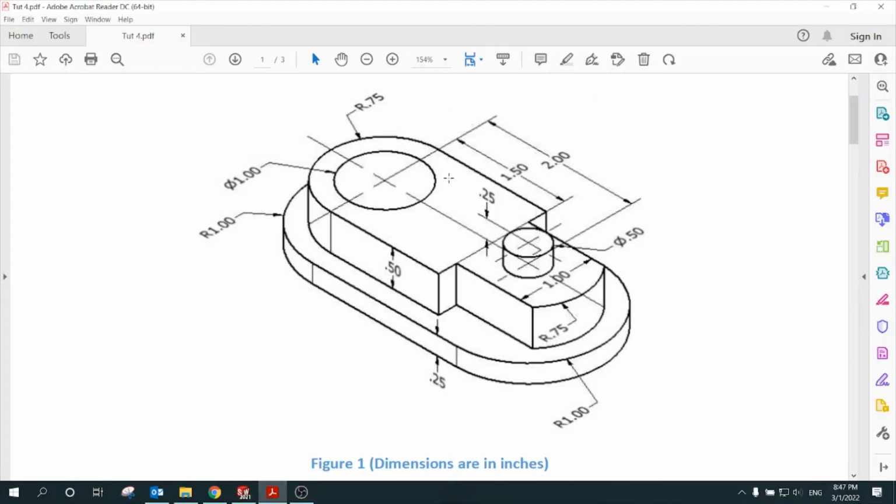Now, how they are connected? The 1.5 diameter circle has a straight line of length 1.5 and then it goes inside for some distance and then it goes horizontally until it meets the circle. Can I calculate this distance? Yes, of course, because the diameter is 1.5. That means distance between line 1 and line 2 is 1.5. This is given to be 1. The two spaces is 0.5. Each one of them is 0.25.